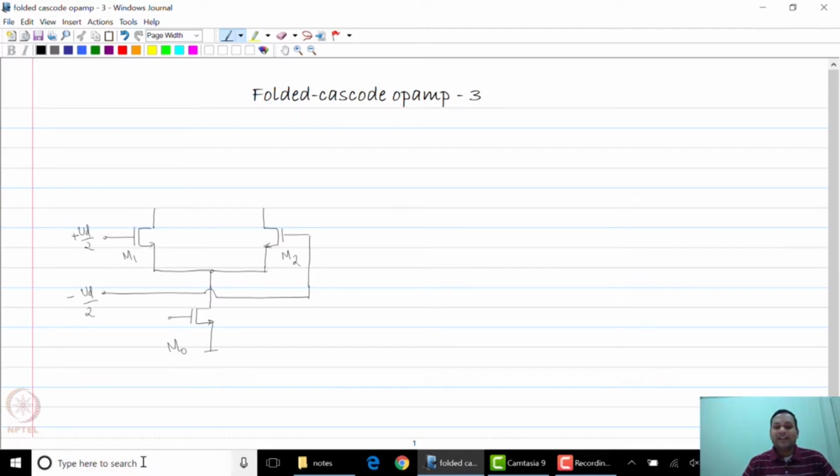M2. Remember that in the single-ended structure, they should go to a node which splits between the common gate PMOS structure, which is folded downwards, and a current source at the top. So if I were to show, the current source at the top would be replaced by PMOS transistors, and at this node you have the splitting of the current between the two paths.